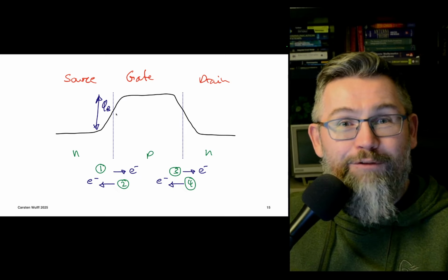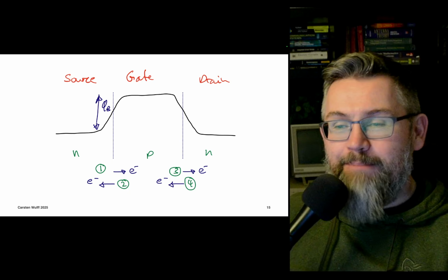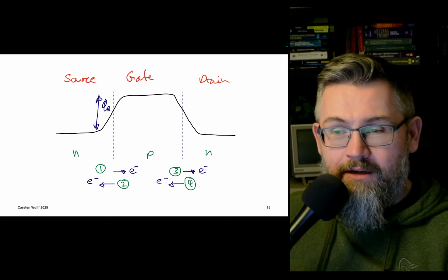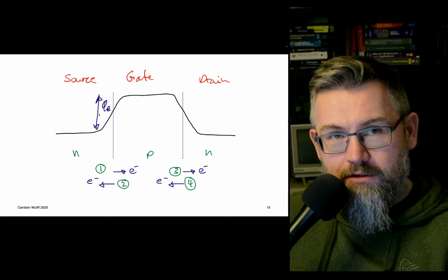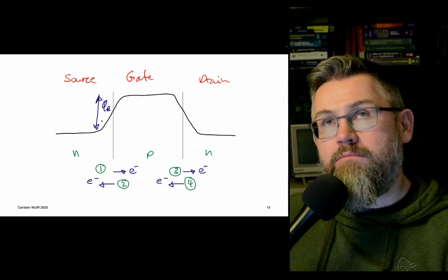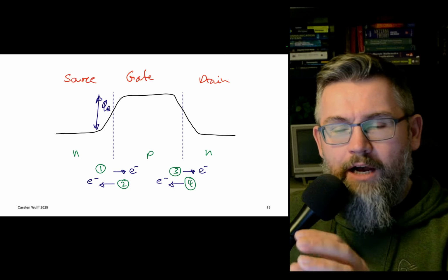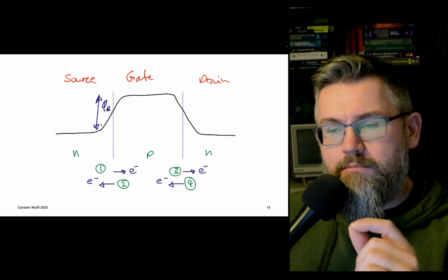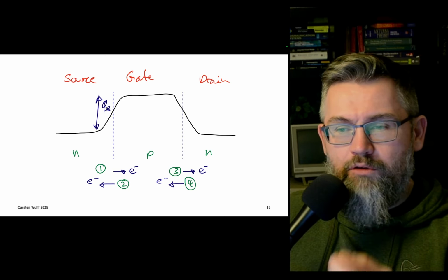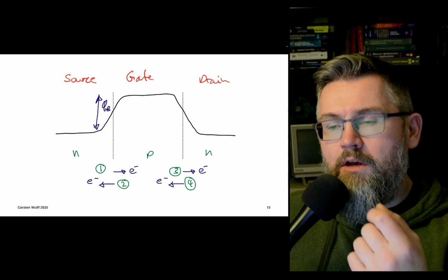There will be bending of the bands. And that band bending is depending on the doping. And that's this sort of built-in voltage that we get. So yeah, I think I have that later in the slides, but we've gone through that before, how to get to the built-in voltage. Now this energy barrier, like Q times this built-in voltage,